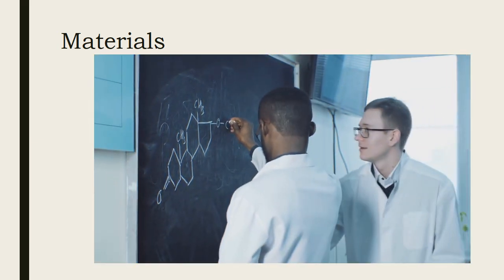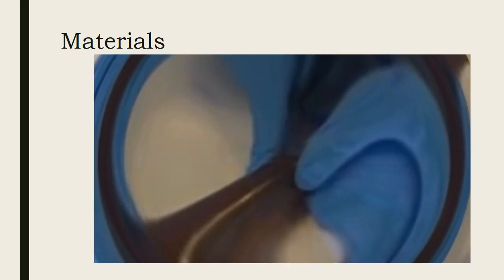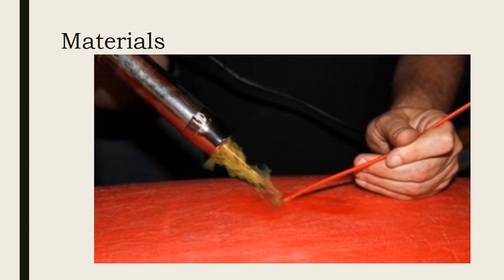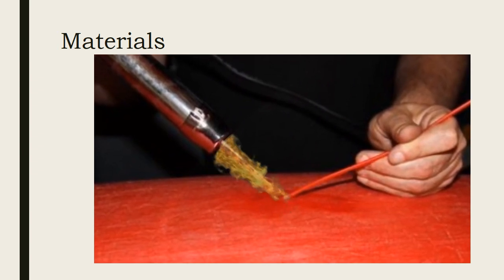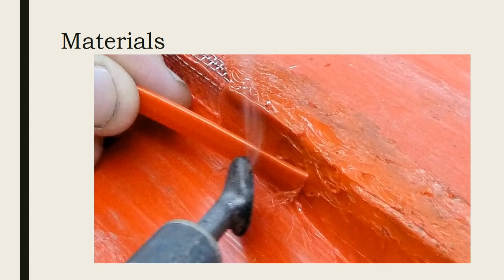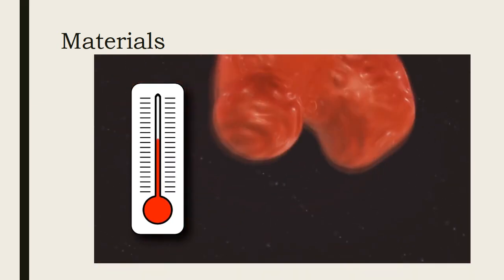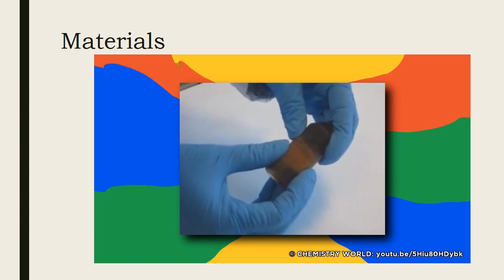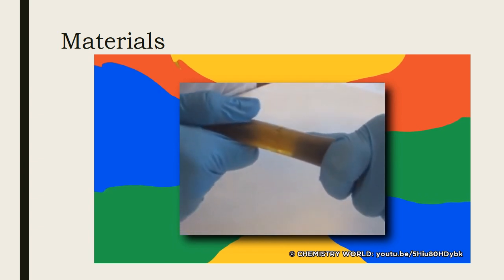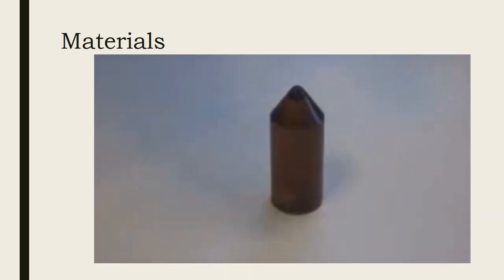Material designers have always sought a strong, hard, and versatile material, which can fix itself on its own. But before this material was created, self-healing plastics would need a stimulus in order to instigate the healing process. For example, certain plastics would repair themselves when heat is applied to them. Contrastingly, this plastic self-heals at room temperature and does so spontaneously with 97% efficiency, meaning 97% of severed bonds will actually repair. This is achievable through the use of aromatic disulfides, which react and bond at normal temperatures.